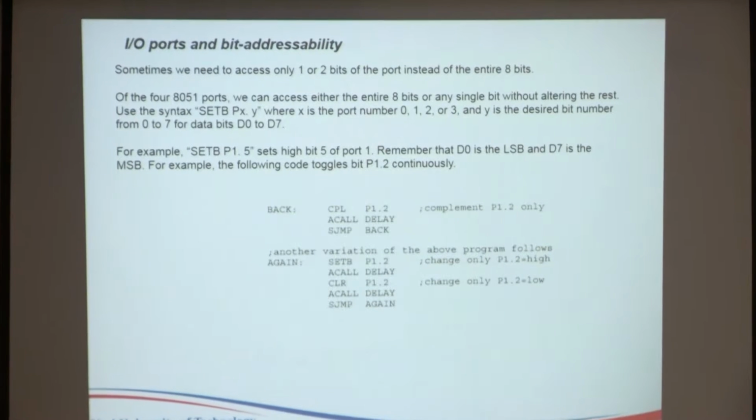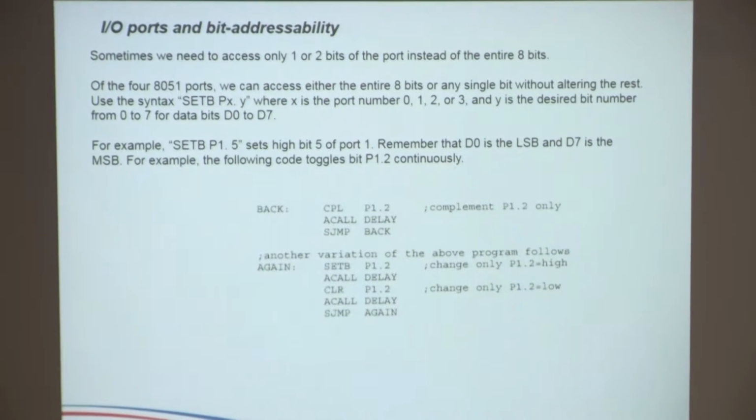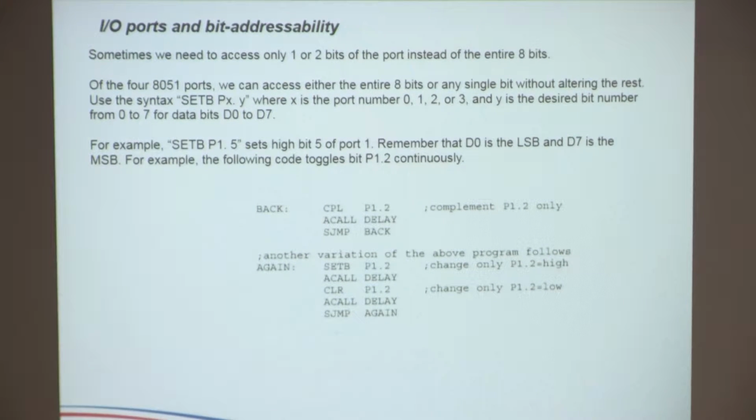Right, now all the I/O ports differ on all the different 8051s, and that's usually where you will decide what size of 8051 family you're going to use, which will be determined in terms of the I/O ports that you're going to need. Because obviously the more I/O ports you have, the more expensive the 8051 is going to become, isn't it so? Right. So for the example we used with the gate motor control, where you would only maybe need 4 I/O ports, then you're not going to use an 8051. That's why they use a PIC there, because it's going to be much cheaper.